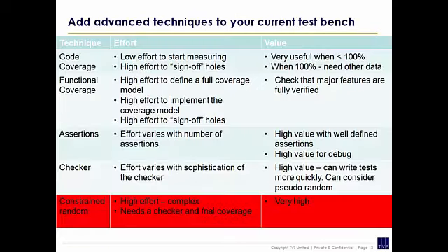Okay? So, here's some of the techniques. And this is my personal analysis of how you can add those techniques. Code coverage. So I think probably most people are doing code coverage already. If you're in a DO254 environment or a compliance environment, you'll already be doing code coverage, probably up to MCDC. Functional coverage you're probably not doing.